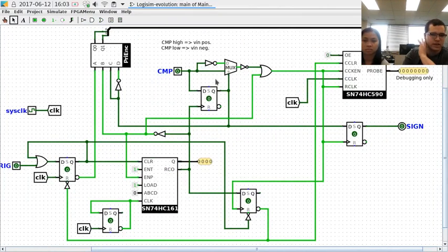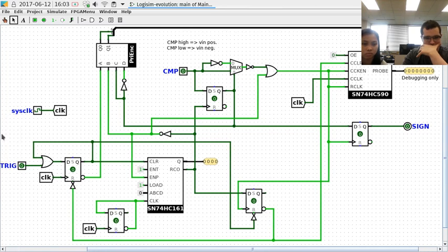So going back to here, for now, we've got basically a trigger line here. That's this trig that turns on the conversion. It starts the conversion process. There is a clock divider in the timer. That was just to get the right timing. The final design runs at 4 megahertz, and so this is a divide by 32 counter that we're using as a timer. So if I were to start this simulation